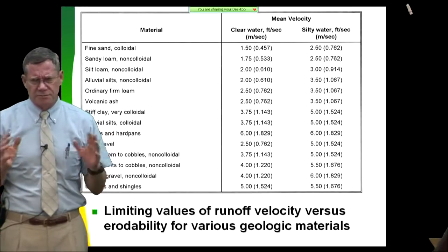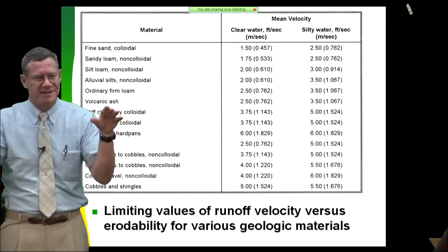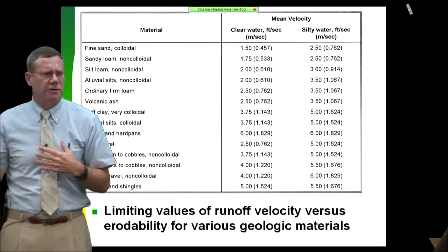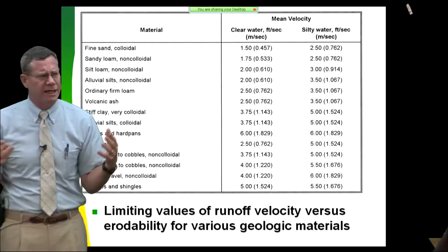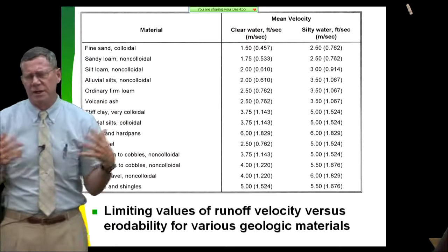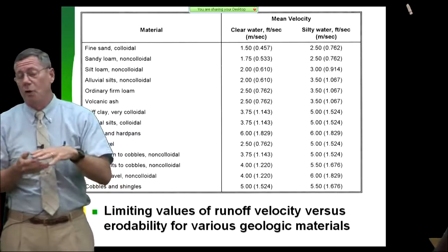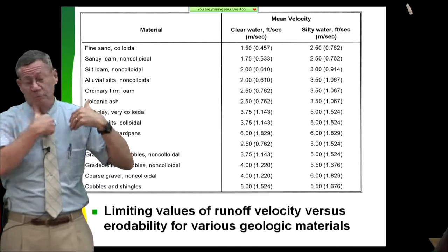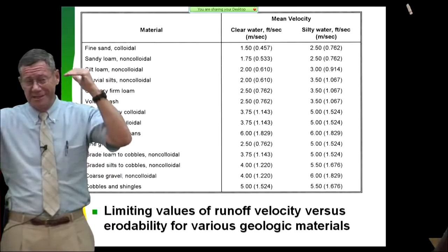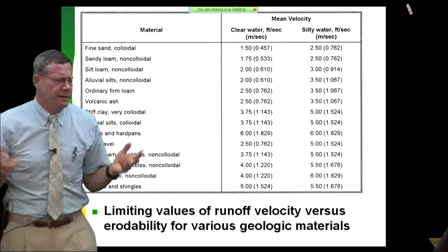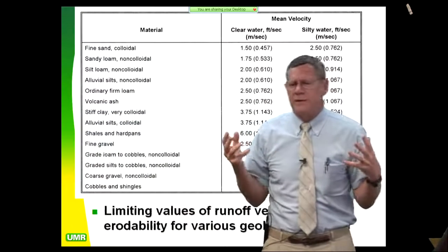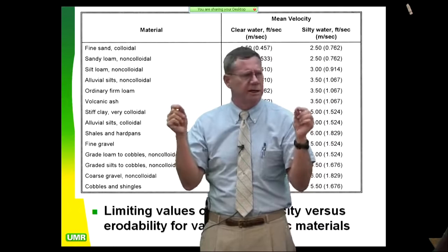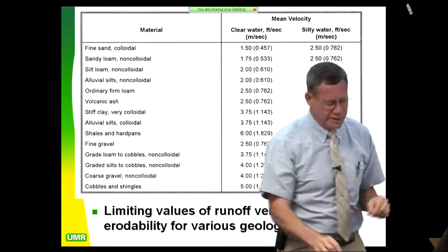So landslide dams are the big thing that's not on most people's radar horizon, and they create much larger floods downstream than conventional floods. So if we go out in the western Grand Canyon today, we look at some of the work the USGS has done there over the last decade, we have catastrophic outbreak floods from the failure of landslide dams and lava dams that are over 2,000 feet deep. These are things that are 5, 6, 7 times the height of Hoover Dam that went blasting down that canyon and left these terraces, and they use optically stimulated luminescence techniques to date those kinds of events. So those are the big events that are out there. If you go to work in the Hindu Kush or the Andes, you will see these terraces everywhere. They're not riverine terraces, they're landslide dam outbreak flood terraces.